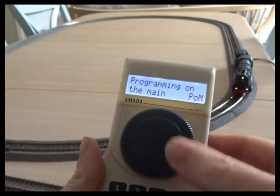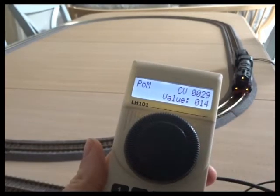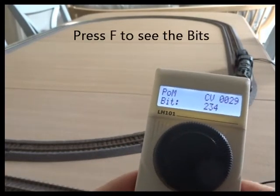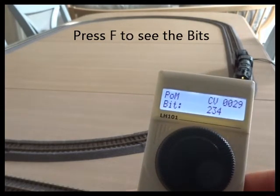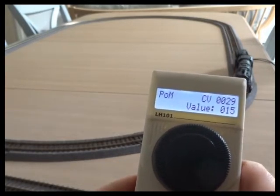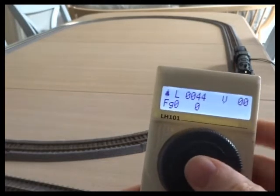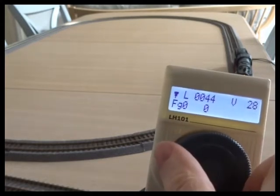We go in, read CV29, value of 14. So it's got a decimal value there, but I'm going to have a look at the bits that are selected. Now the first bit changes the direction of the loco, so if I activate that, send it, escape, escape. Now I've reversed the loco, so my throttle says it's going forward, but reality is it's going backwards.